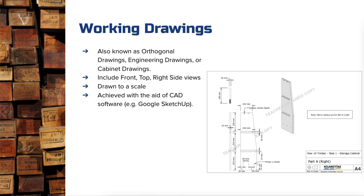It's probably becoming much more technical. It's probably starting to comply with the Australian standard AS 1100 for technical drawing. It's probably being developed in computer-aided design software, CAD software. Okay? It will usually include a front, top, and right side view. It will usually include dimensions, and it will usually be drawn in a scaled fashion.